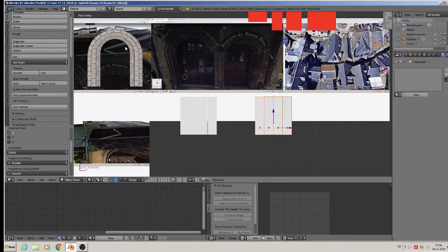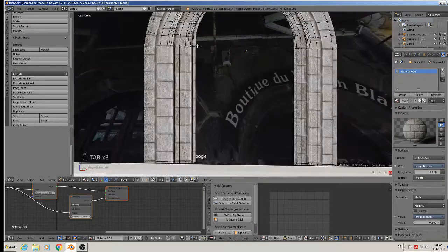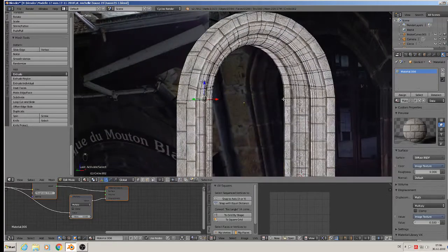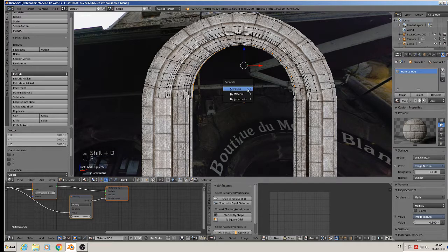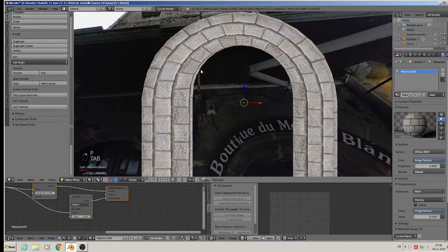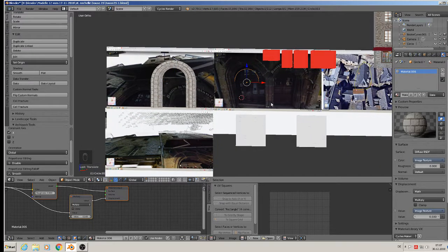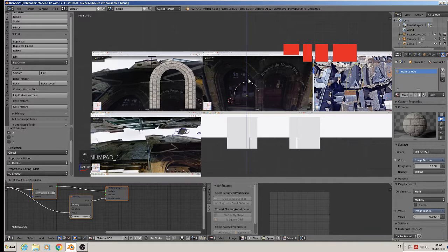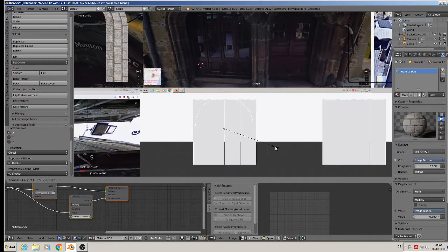So we take that roundness as a cutting object. That means we take here the last part and Shift D, make a duplicate, P to separate the selection, then object mode, and we have the original size, and that we bring here over and scale them up so that it fits there completely. That is there.